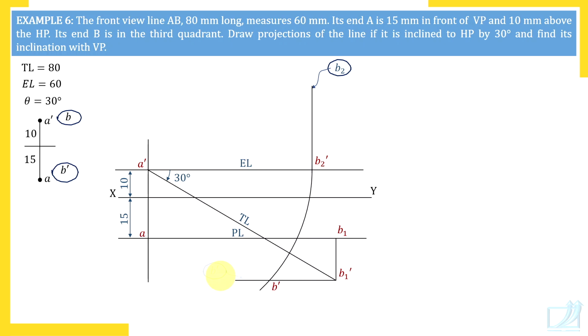So erase that rough label, because we have found out B dash. We have used the compass. We got a new point. Now leave the compass and through B dash draw a vertical line for B. B is above the XY line. That's why I've extended that line upwards.